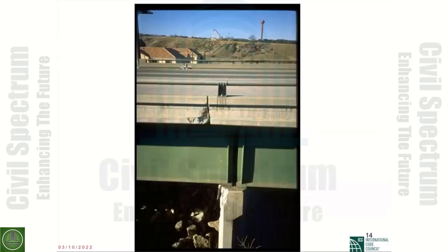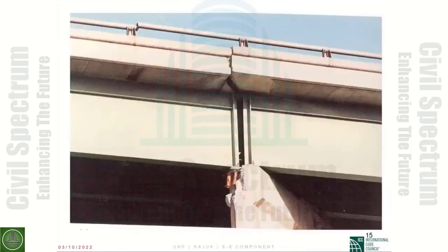This is the same thing for a steel bridge, and that's what you see on the top of the bent cap, where the steel plate girder bridge wanted to move, and these things will become part of the seismic load path. And if you look very carefully here, you see the anchor rods, and you see the lack of reinforcement surrounding the anchor rods, and that has failed.